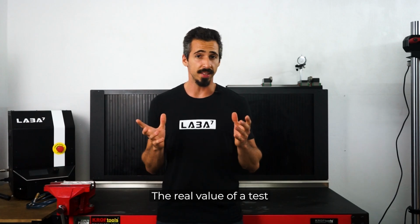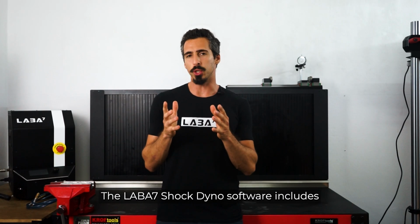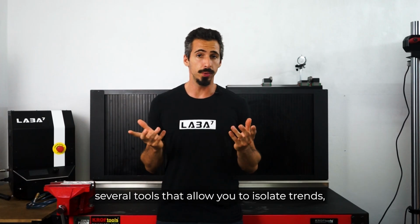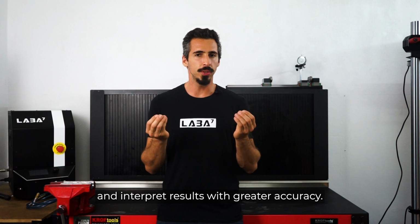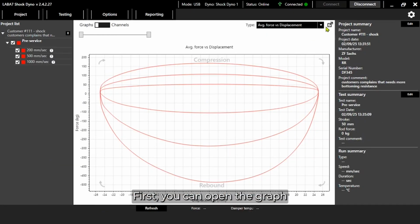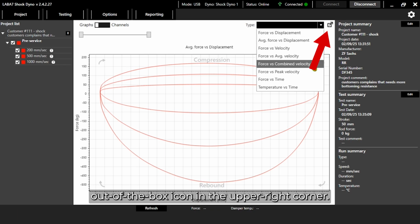The real value of a test isn't just collecting data, it's being able to explore it. The Laba 7 Shock Dyno software includes several tools that allow you to isolate trends, compare variations, and interpret results with greater accuracy. First, you can open the graph in a separate window by clicking the arrow out of the box icon in the upper right corner.